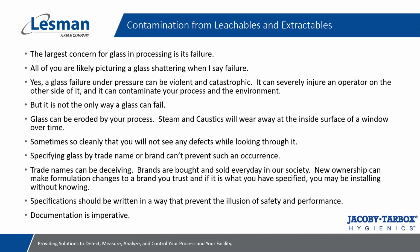So you've taken a window that maybe was 15 millimeters thick, and it was made that thick because that's what the pressure temperature calculation said that it needed to be to withstand the pressure. And now it's half as thick, and it's still seeing those same pressures.